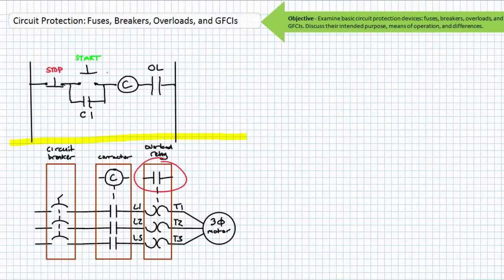When the control circuit tells the contactor to open, the contactor opens, and at no time did the overload itself open. Only the contactor opens and closes. The thermal overload is again just a sensory device that interacts with the control circuit via the auxiliary contact. Only after the thermal overloads have cooled and reset will commands from the control circuit allow the contactor to close again. Understand, this is the quickest of explanations, and I don't blame you if you're scratching your head a little.